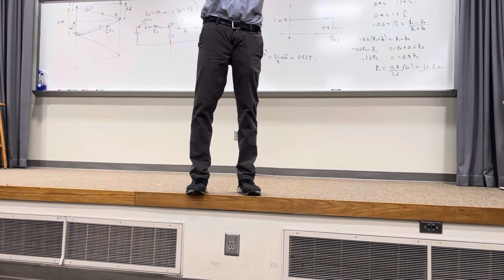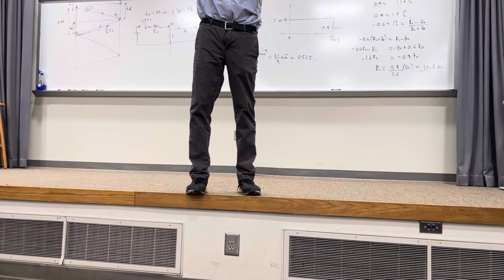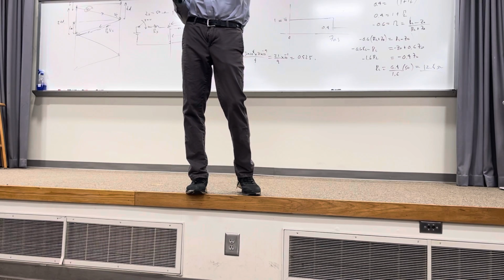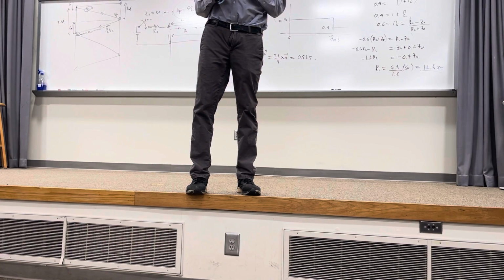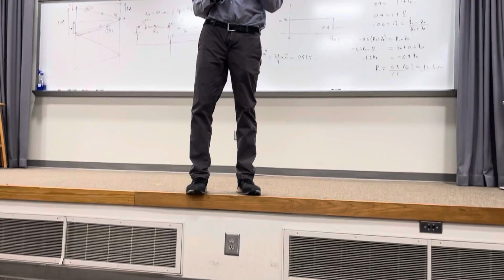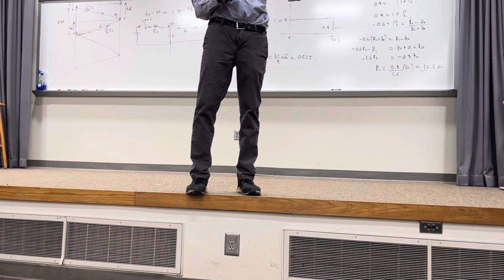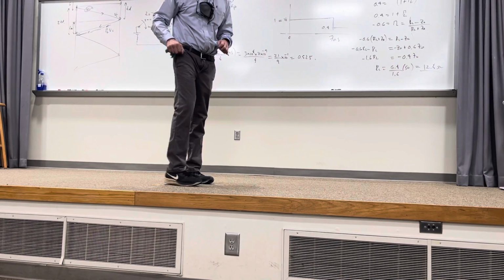As the wave continues its persistence there, it looks closer and closer to a short circuit. That means the reflected pulse from an inductor would be like an open circuit in the beginning, very high, and it would die down exponentially. I don't go into that, but almost any kind of TDR work you're going to be dealing with is going to have just resistive loads. If they have a combination, it becomes a lot more complicated because most things aren't just inductors or just capacitors. They're combinations, and then it gets to be a much more difficult problem.